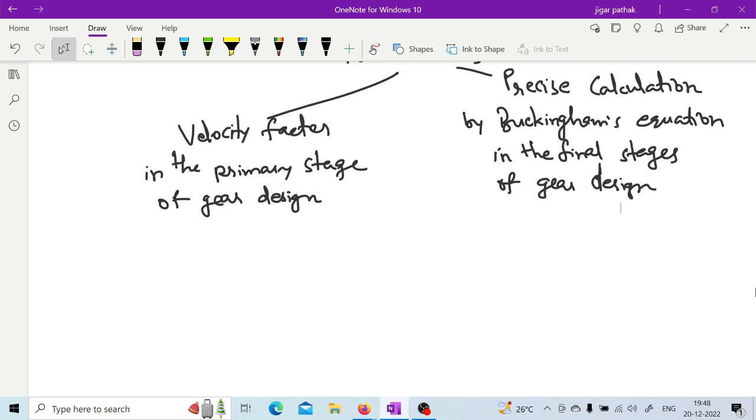If there is uniform torque, hypothetically, then no stresses? No, stresses will definitely be there. The service factor we need not consider if a constant torque is being transmitted. The stress cycle is a different thing. It is because we are considering only a particular pair of teeth in mesh with each other. During one revolution that pair will be in contact only once, so there is one peak in that cycle. During that point they will be under stress, and during the remaining revolution of the gear, there will be no stress.